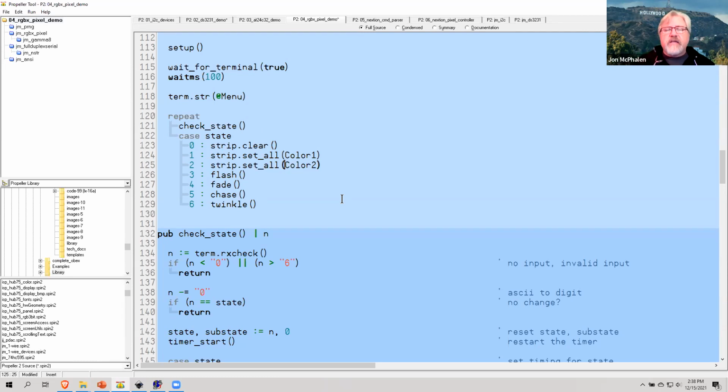Again, in my laser tag project, the whole system runs this way, constantly going through and checking: do I have a radio input? Do I have an infrared input? And then whatever is going on in that particular state, iterating through. Sometimes there are substates in that from displays or sound effects or whatever. It makes the system easy to manage once you get a handle on the whole state concept.